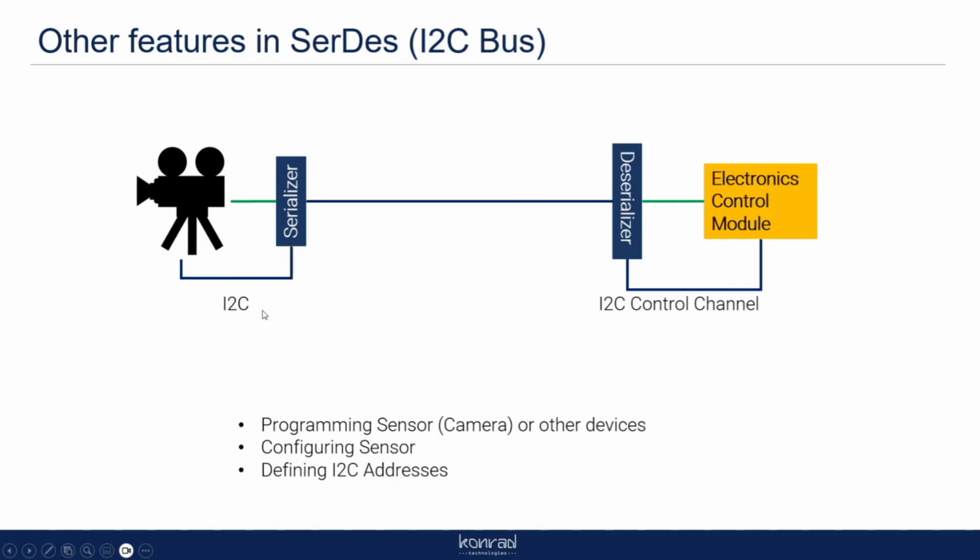So one of the things we would do is read in an image and pass it to a DLL that they provided us because they didn't want to give us all their IP. From this DLL, it would give us an updated value that we needed to tell their camera over I2C to set the exposure control to. So as we were driving along recording data in the loop, we were able to change the behavior of their camera based on the images that were coming in. This was something that they wanted their ECU to be able to do, but they also wanted to test some of their algorithms as we were running in vehicle.